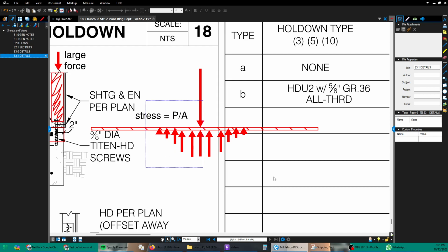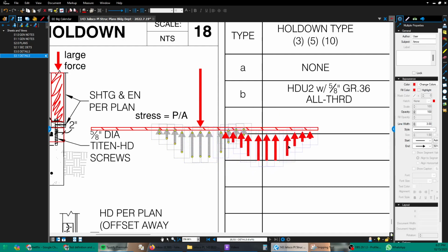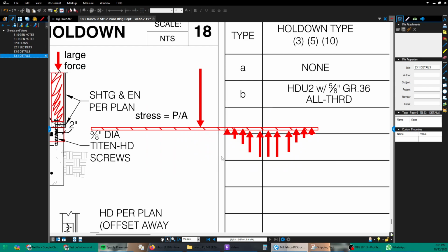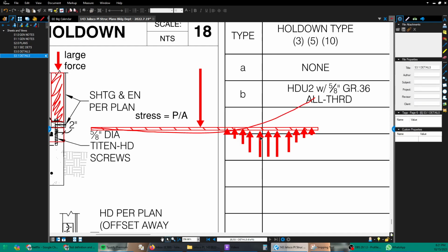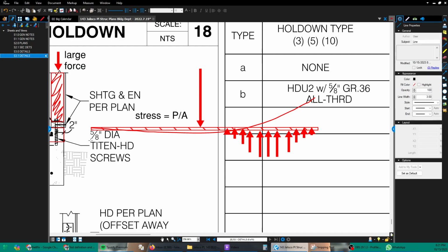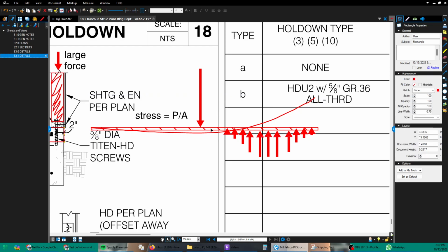And we could have some localized area of soil swelling happening over here, and we don't want to do this to the slab. We don't want that soil swelling to pick up a corner of the building. We want the building to remain rigid like this. So maybe the building gets lifted up somewhat at the corner, but there's not a huge amount of distortion of the foundation shape that will curve the foundation and then bind up a bunch of doors and windows.